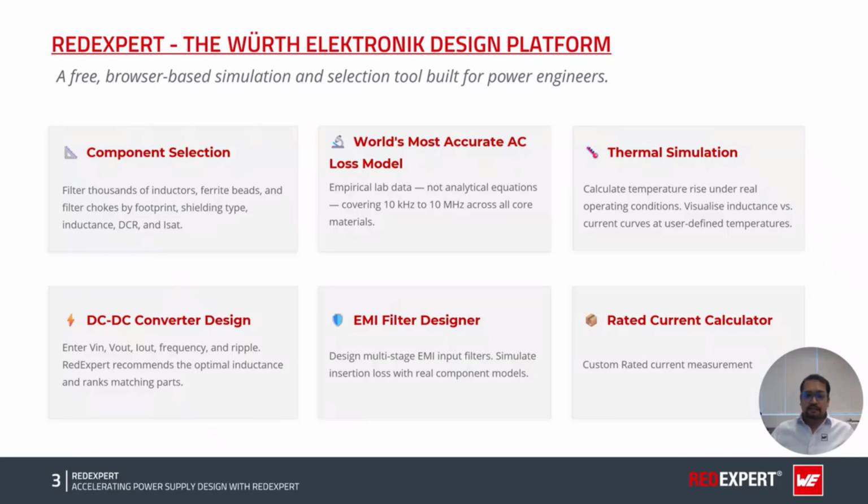Second, DC-DC converter design. You just enter your input voltage, output voltage, load current, switching frequency, and REDEXPERT recommends the optimal inductance and ranks all matching components for your exact operating point for that DC-DC converter. Third, you can also design multi-stage EMI input filters and simulate insertion loss using real measured component models, not idealized curves only.